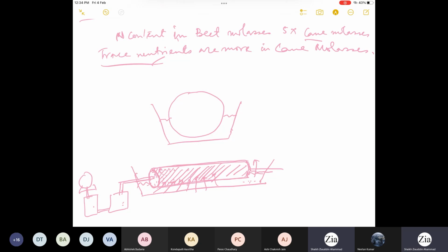This slurry is a solid-liquid mixture, and whenever you rotate the drum, all the surface will get exposed to this liquid-solid mixture. Because of this suction pressure, liquid will move through, because the pore size of the membrane filter is such that it will not allow the solid to go in, but it will just take the liquid. The liquid will be collected at the bottom, and from the bottom you have another line to drain the liquid. There you'll also have another pump to suck the liquid from the cylinder.